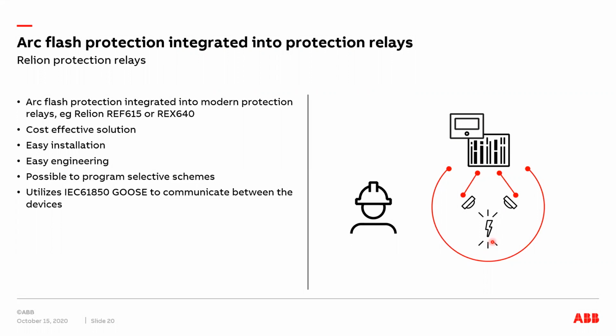By integrating ARC flash into the normal protection, it's a very cost-effective solution. If you're anyway changing the protection relays, you can add on ARC flash protection.